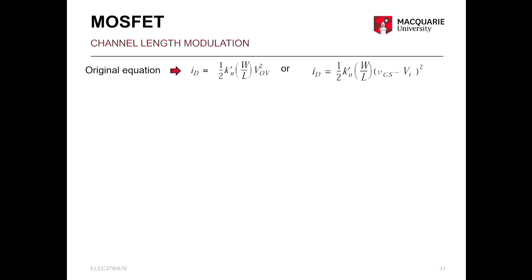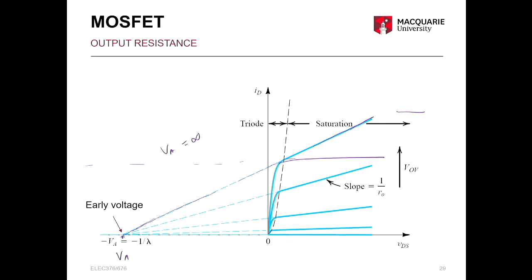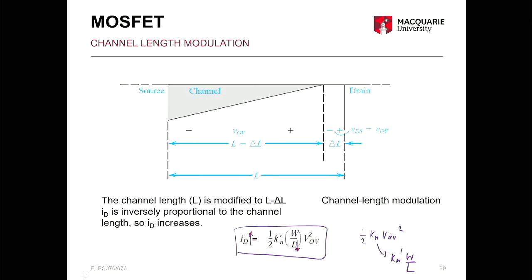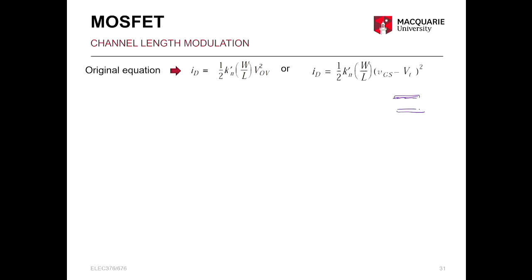Even without a channel, it is like dielectric breakdown. If you have a dielectric which does not conduct current, and you apply a voltage across it, no current flows, and you apply more and more, at some point it just punches through.